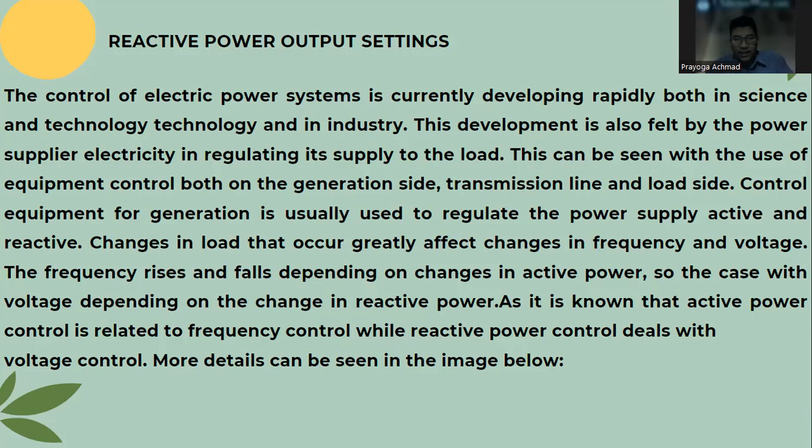So it is the case with voltage, which depends on the change in reactive power. Active power control is related to frequency control, while reactive power control deals with voltage control. More detail can be seen in the image below.